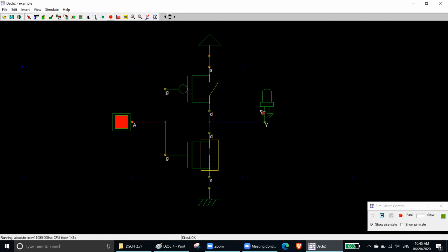So again, what is happening here? At one pin of the LED, there is a ground. In another pin of the LED, there is also a ground. Can you see that? This ground is connected directly to one pin of the LED. Another pin is already grounded. So your LED has two grounds in its two pins. Okay, so that means your LED is off.